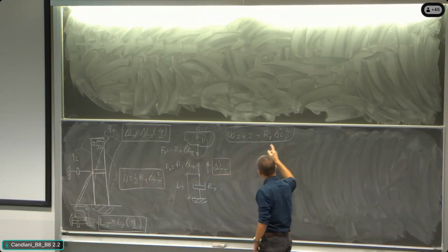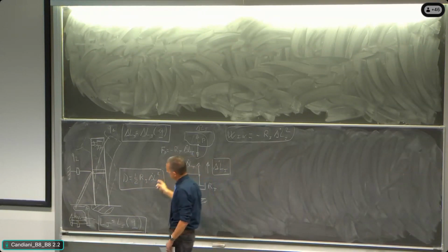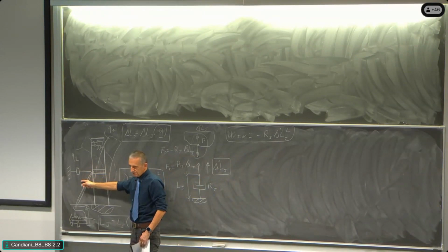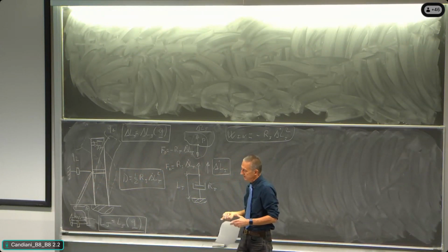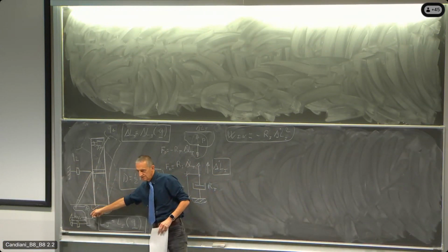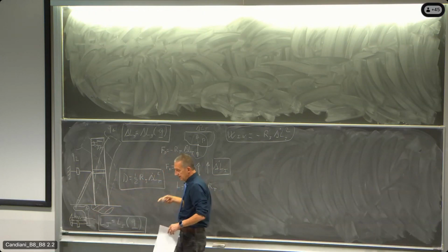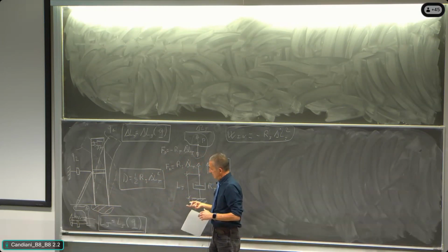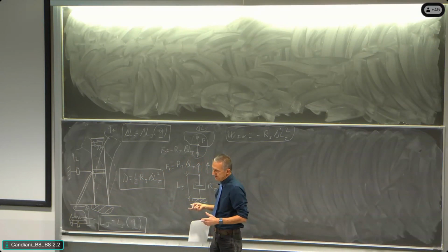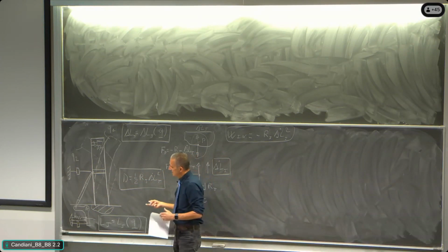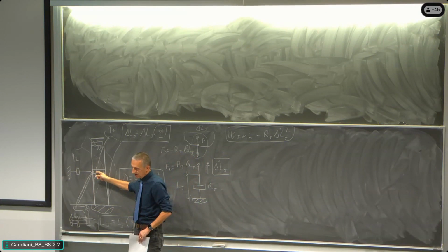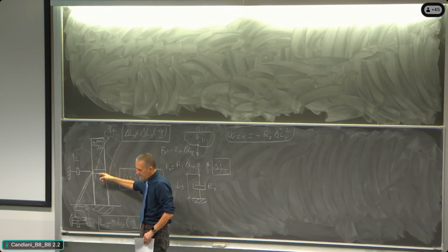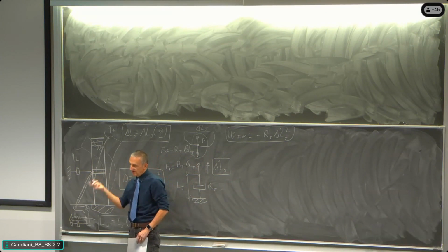Then delta Lj, you can understand, is linked to the movement through the kinematic relationship, to the kinematic properties of the mechanism, or it is linked to the modal behavior of the system. So the modal behavior of the system is stating how much delta Lj increases when the specific mode of vibration we are speaking about is moved by the principal coordinate that is driving it, all right?